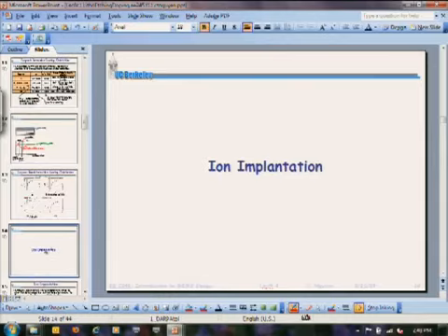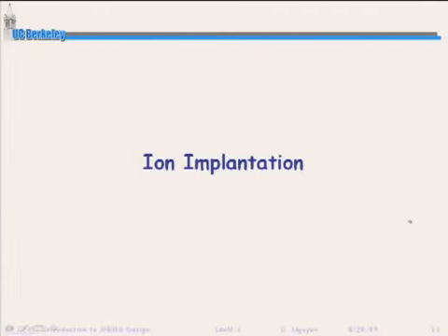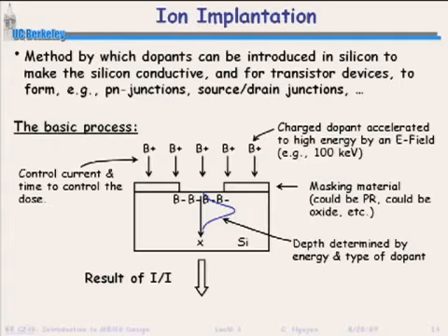And so here's what's happening. Ion implantation basically means you're taking an ion of the dopant that you want to implant. Since it's an ion, it has a charge, so you can apply an electric field and accelerate it with very high energy into the silicon. You're basically bombarding the silicon with this ion, and it's going to push its way into the silicon, and most of them are going to end up at the average distance in, which is called the range.